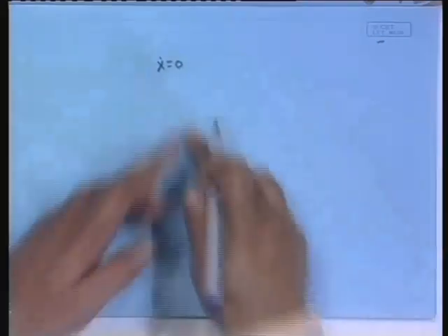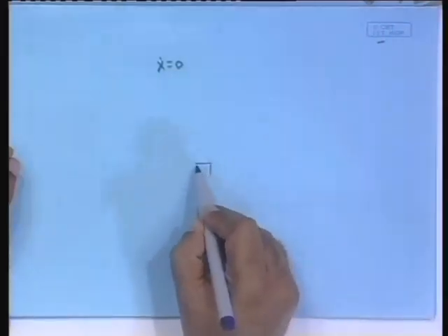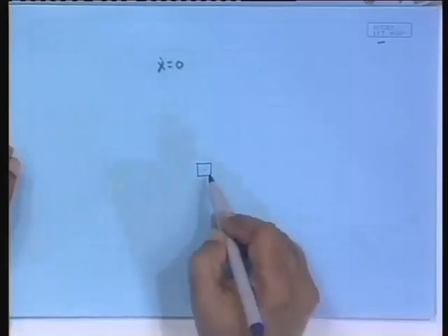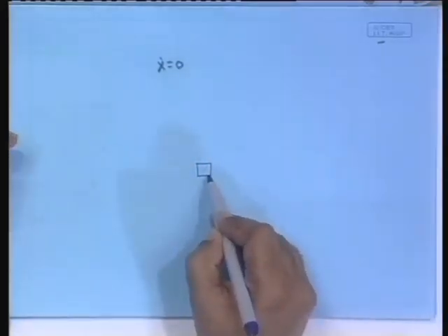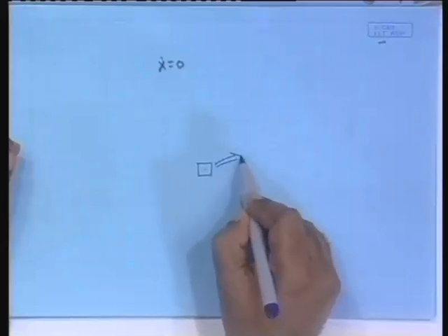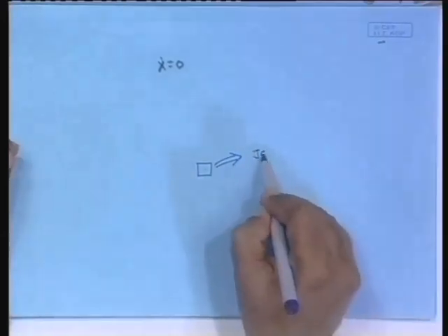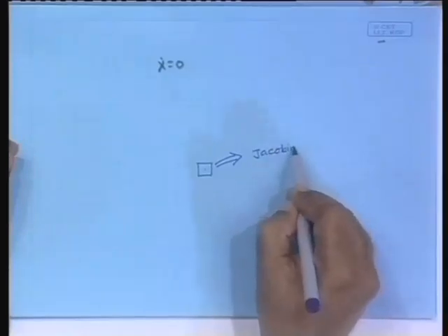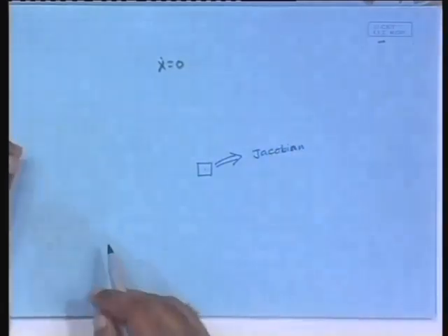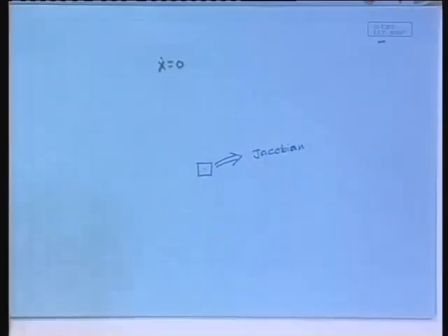These are given by x dot equal to 0, where x is the state vector. Solving the right hand side, we had obtained that, and from there we said that fine, we have now identified that this is the equilibrium point, and we will look at only the local neighborhood of that, and in that neighborhood we can locally linearize it. So, we used the Jacobian to linearize that. Here the Jacobian would be representing the local linear behavior. So, we obtained a linear set of differential equations.